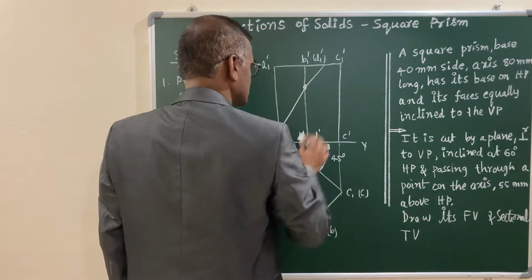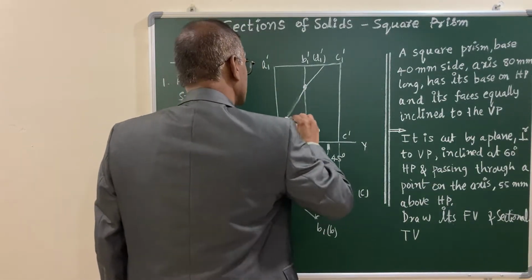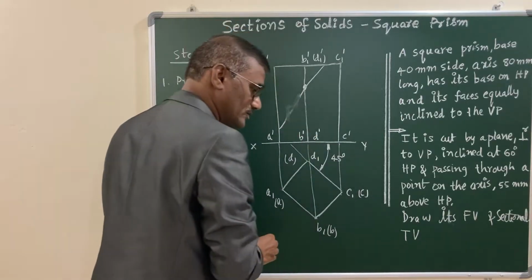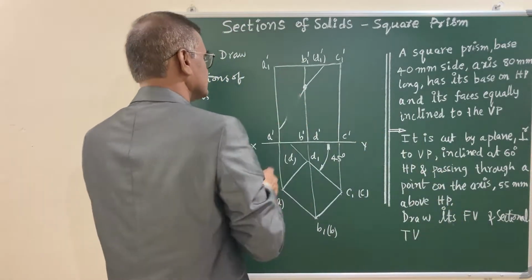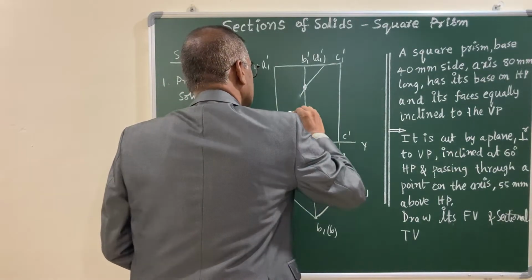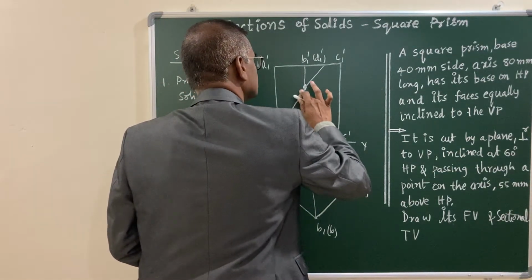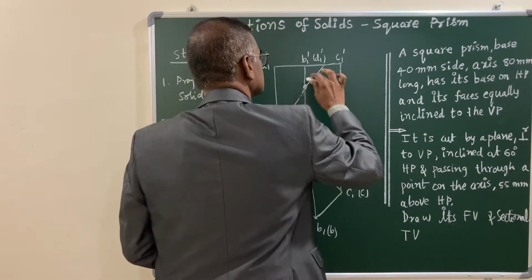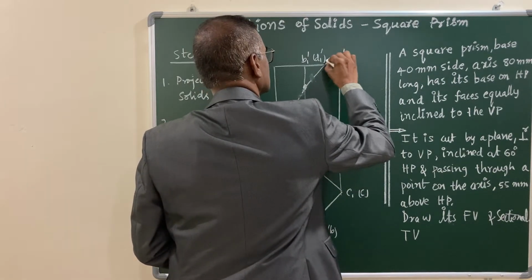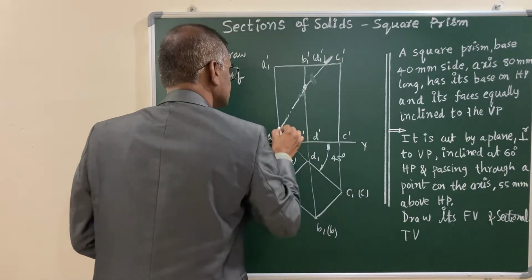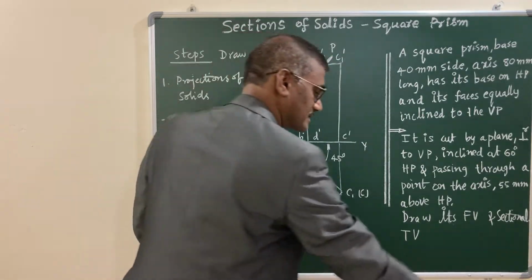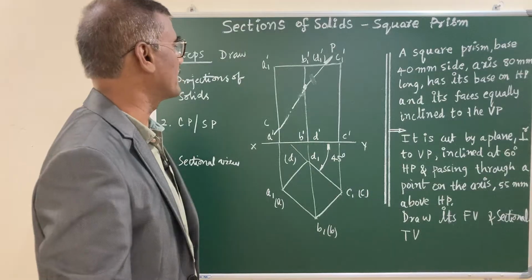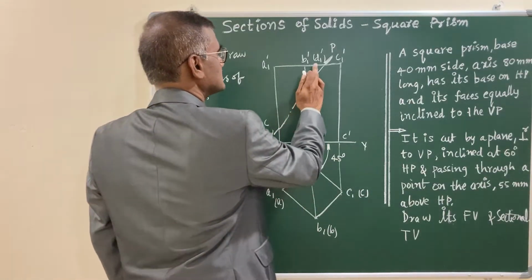And this notation, as you know, the standard notation is long chain line. You have to make use of this long chain line, that is axis notation, and ends you have to make thick and write down CP with the capital letters that indicates your cutting plane. So this is exactly the step.